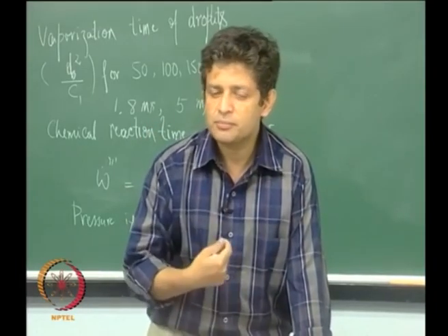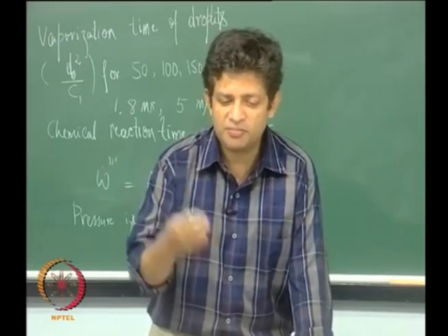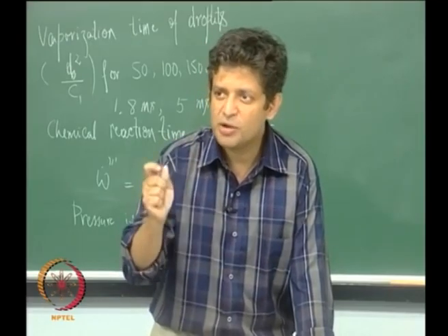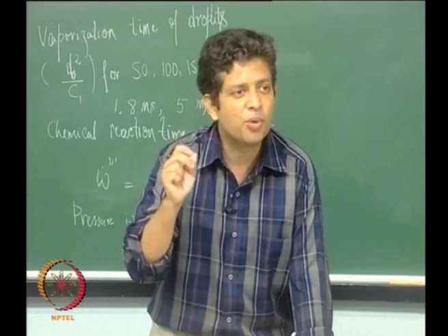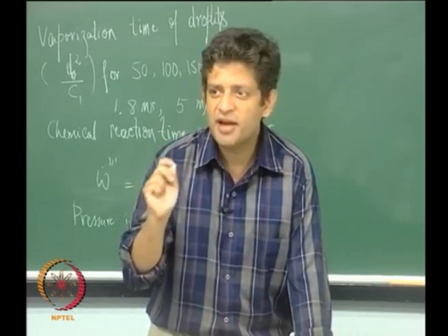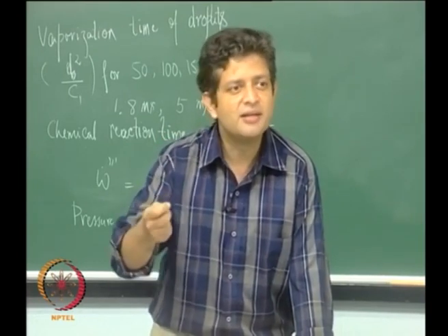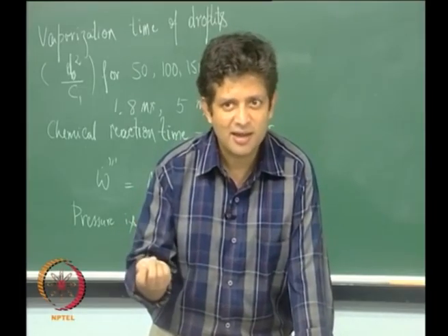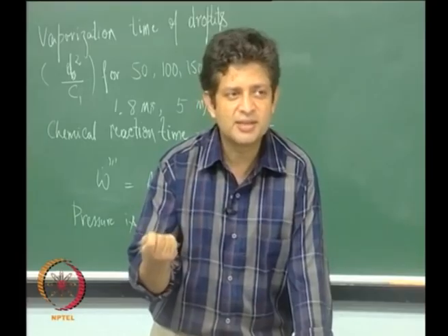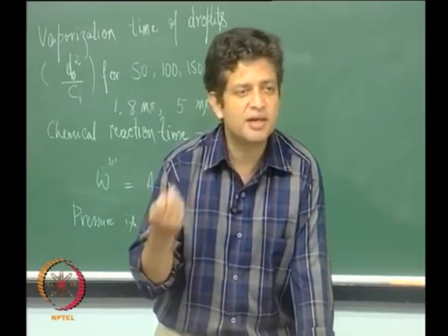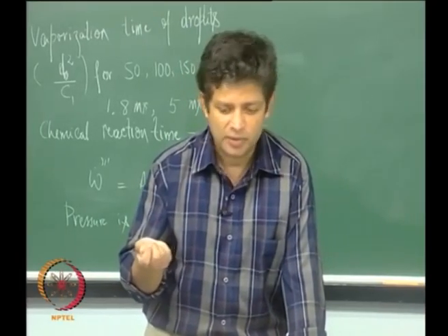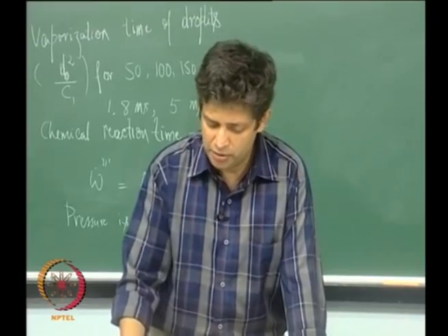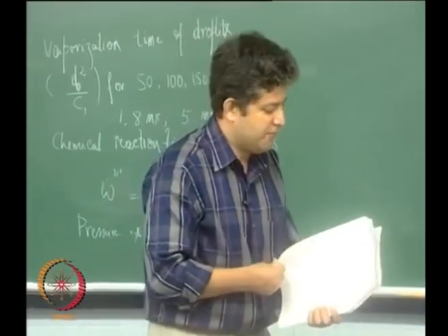So you need to make sure that it is atomized, that is, broken into very fine droplets. These fine droplets will then evaporate fast, the reactions take place in the gas phase, and these get completed very, very quickly. Now the vaporization time